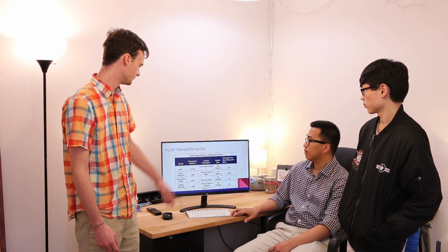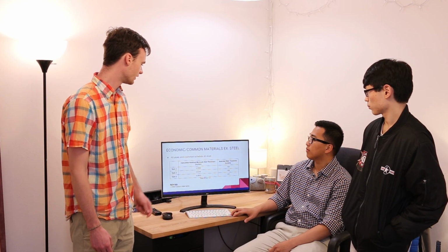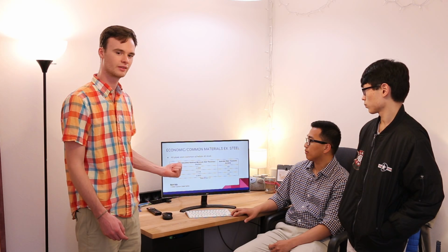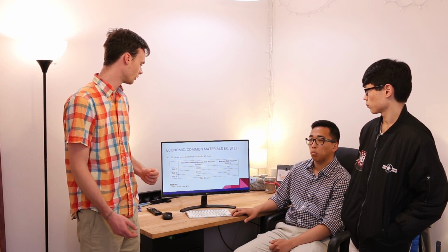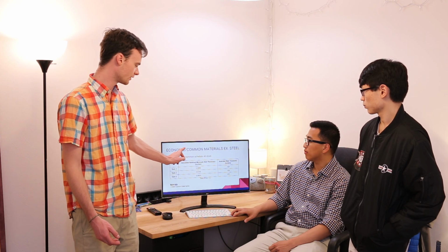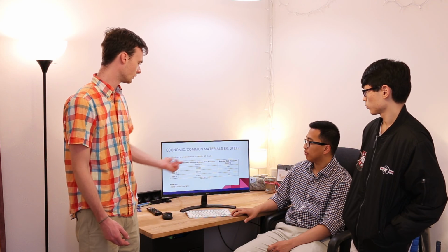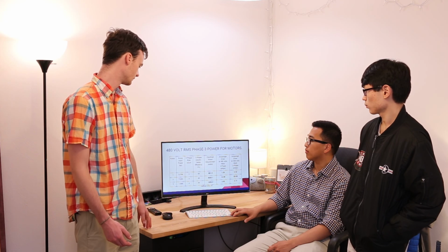So you have the different gallons per minute. Over here is the selected pipe and tank thickness. We used the size of the tanks and the density of the fluid to determine the minimum wall thickness. This minimum wall thickness is with a factor of safety of 2, and obviously all these sizes are not standard sizes, so we upscaled it to 1/8 of an inch as a standard size.